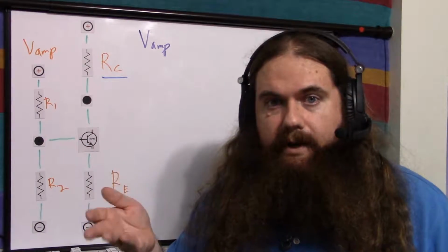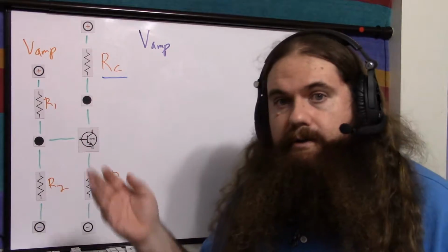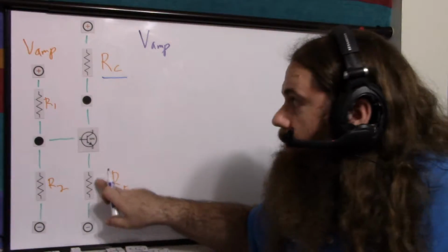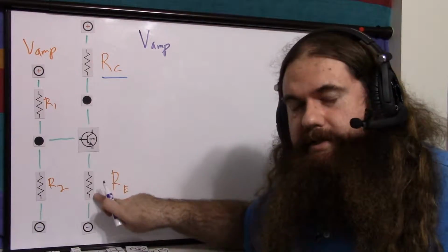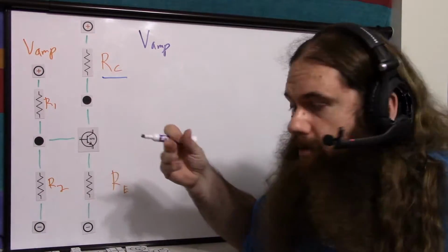So if you don't care about the power usage, buy really strong resistors and transistors and do it this way. You'll get the best quality. Even better, if you can leave off the capacitor here, you'll get even less gain, but less distortion. So, multi-stage with power transistors, and there you go.